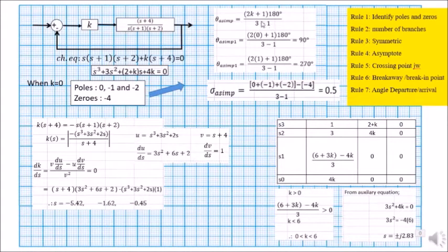In this case, we have 3 poles and 1 zero, so we put 3 minus 1 here, which becomes 2. When we put k equal to 0, we get 90 degrees. When k equal to 1, the value becomes 270. When k equal to 2, the value becomes more than 360. So we just use these two angles, because the angle of asymptote must be less than 360.